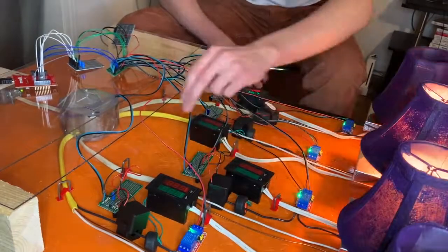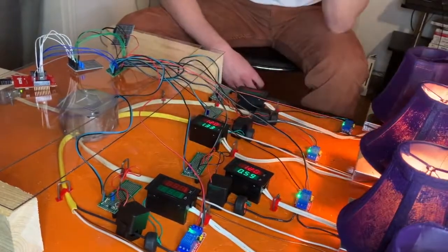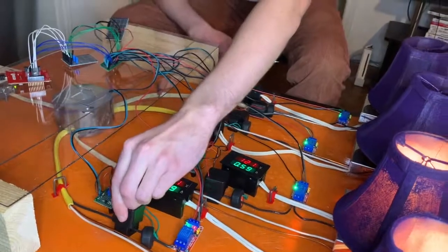We also used relays, we'll talk about those a little later, to cut the power on and off. In the midst of all of this, we developed a hardware shield, and we used this hardware shield to separate our high voltage and low voltage wires so that we wouldn't have any crosstalk happening.